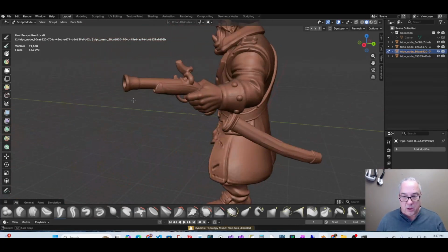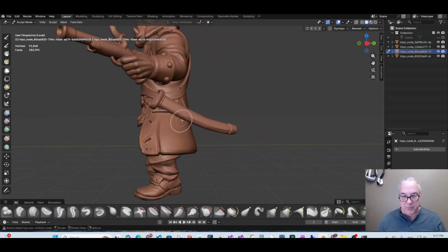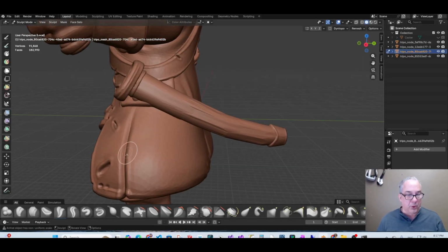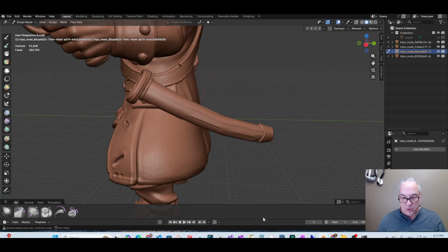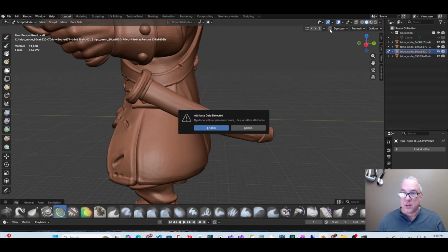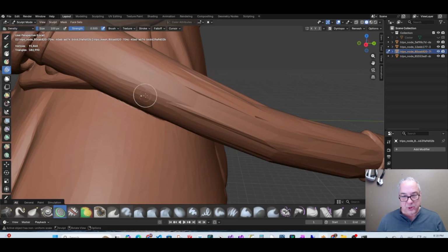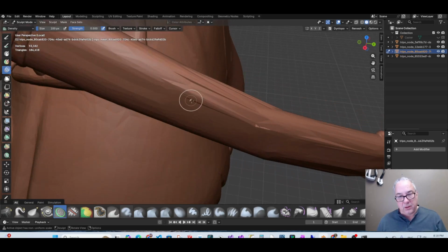We've got our sheath. Let's fix where I did that stretching. We're going to go back into sculpt. We're in sculpt mode, so we're going to go back into our Dino Topo brush. Apply, and we're just going to where I stretched this geometry. We're just going to clean that up a little bit. Dino Topo and smooth. Remesh.